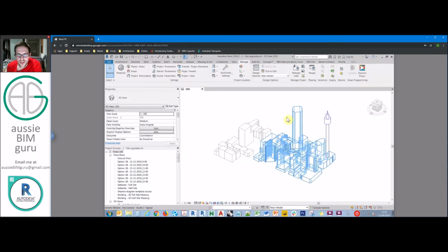And the reason I've done this is because it's much easier for Dynamo to process geometry that's native to Revit, and probably more simple than a CAD file, because CAD doesn't always have closed surfaces. There's a lot of issues with how Dynamo interprets it, so I just took a little bit of time to model my site. This probably took me about 10 minutes to do, so I think it's worth the effort. The good thing about this as well is it looks a lot better when you do a 3D shot in Revit, because you can actually interact with these elements as native geometry instead.